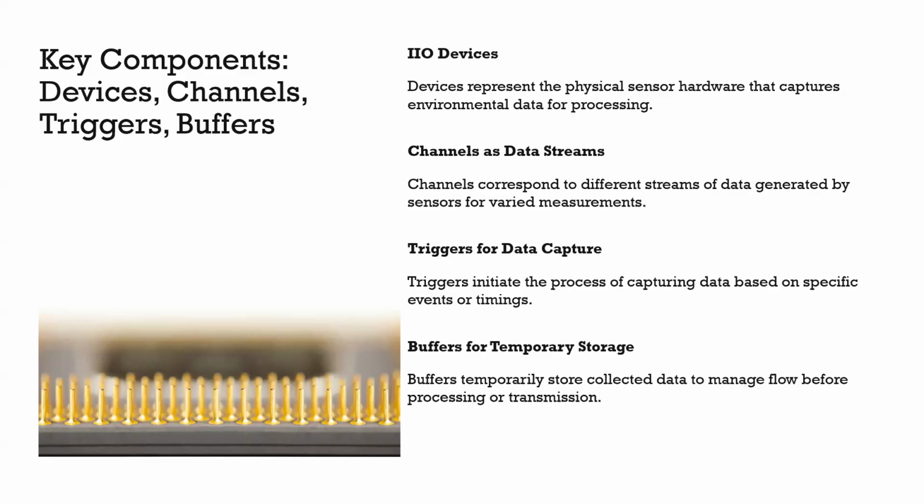So on one side, the trigger keeps on getting the data from the sensor, and the buffer management keeps on filling the circular buffer, and on the other side, the user application keeps on reading the data from the circular buffer. So if the user application is running, there is very little chance that you will miss the data, because these circular buffers are configurable as well as large in size. Basically, if you know that you are missing the data, you can even reconfigure it to increase the size of the circular buffer.